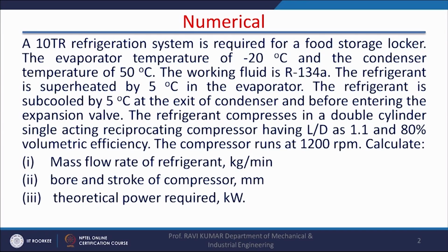A 10 TR refrigeration system is required for a food storage locker. The evaporator temperature is minus 20 degrees centigrade and the condenser temperature is 50 degrees centigrade. The working fluid is R134A. The refrigerant is superheated by 5 degrees centigrade in the evaporator while coming at the exit of the evaporator. The refrigerant is subcooled by 5 degrees centigrade at the exit of the condenser and before entering the expansion valve.